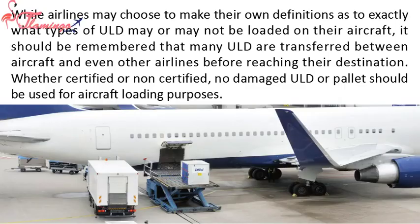While airlines may choose to make their own definitions as to exactly what types of ULD may or may not be loaded on their aircraft, it should be remembered that many ULD are transferred between aircraft and even other airlines before reaching their destination. Whether certified or non-certified, no damaged ULD or pallet should be used for aircraft loading purposes.